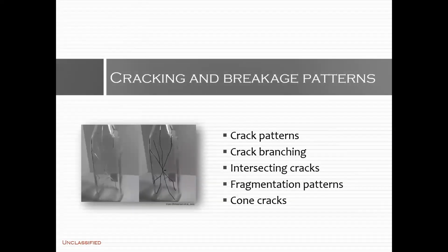Once a fracture initiates, it extends and propagates under differential stress conditions, with the path depending on a number of intrinsic and extrinsic factors. At the origin, a crack will be straight and will propagate normal, or perpendicular, to the direction of maximum local principal tension.